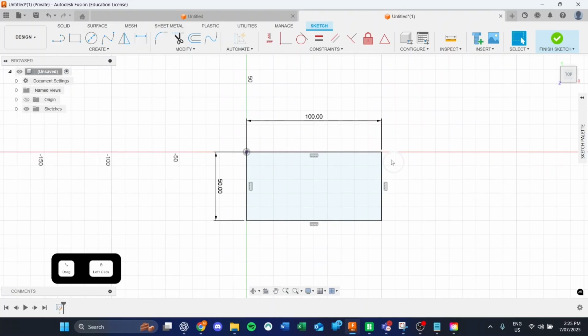It's important to make sure your sketches are fully defined. In Fusion 360, a fully defined sketch will have black lines, while undefined sketch or unconstrained geometry will appear blue. This helps ensure your designs behave correctly. A black sketch is a happy sketch.